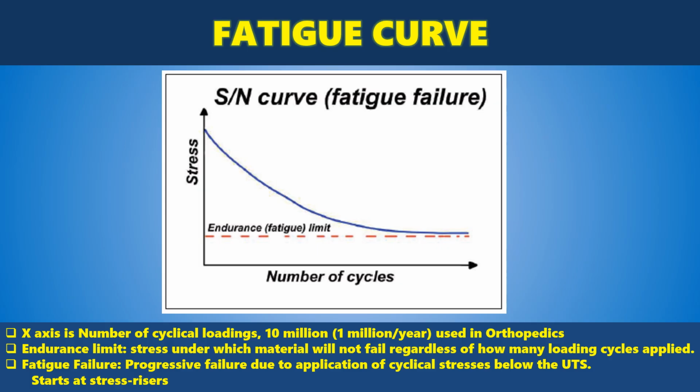The SN curve represents the material's performance under cyclical loads. It plots the stress magnitude, or the log of the stress, on the y-axis against the number of cycles in millions on the x-axis.